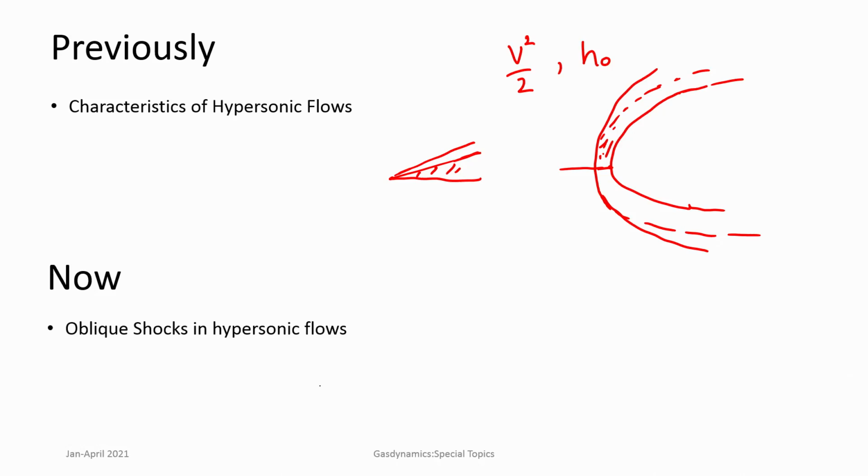We have various such physical effects like very high temperatures. As a consequence, you may have chemical reactions. Air as a simple mixture of nitrogen, oxygen and other gases may not remain the same. It may undergo chemical reactions, even ionization. So, when these physical features become very important, then we call the flow hypersonic, which typically occurs for Mach numbers greater than 5.